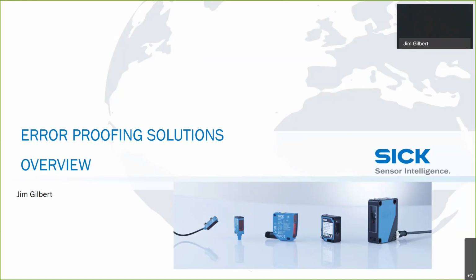Today, we are going to look at error proofing, and one of the highlights we're going to look at today is SICK's new sensor called the WTT4S. It's a time-of-flight sensor in a very small body style. But before we get into that, I want to share a few different applications which we found very critical, and depending on what sensor you select, it can really influence the behavior of the application and the success of the process. So with that said, I'm going to look at a couple applications to different types of sensors. One is a background suppression sensor, and we'll contrast that against a time-of-flight sensor that uses a different technology to detect objects.